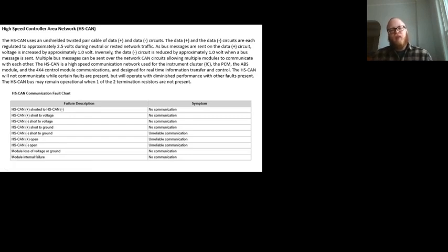So if we turn the key on and just stuck our meter into the data link connector and measured voltage, we'd come up with an averaged voltage, because our meter can't keep up with the time frame at which our modules can talk to each other. It just averages the stuff out. We'd see somewhere around 2.5 volts. It'd probably be fluctuating slightly as the different messages came by, but that'd be something we could do to see if our network's working at all without even having to hook up a scan tool to it, which can be convenient.